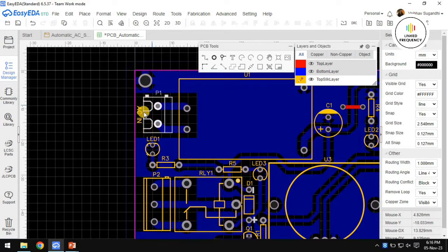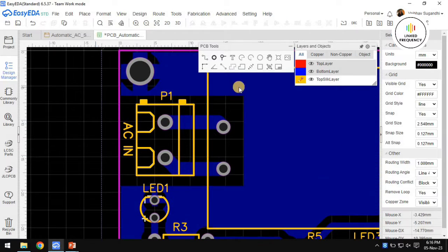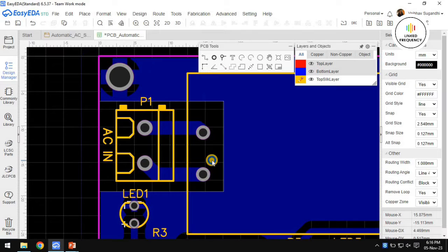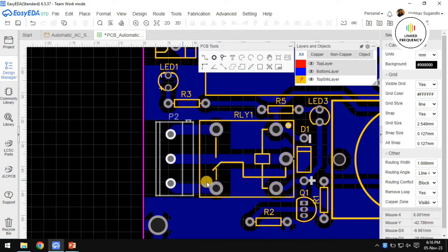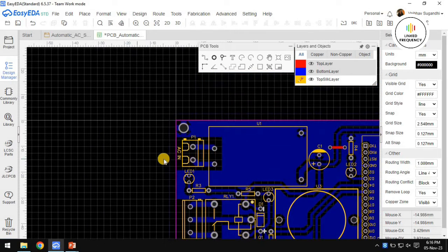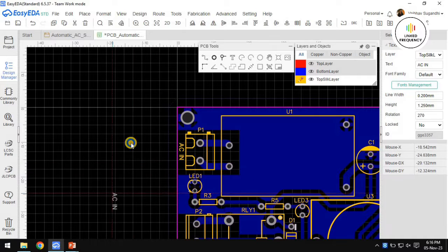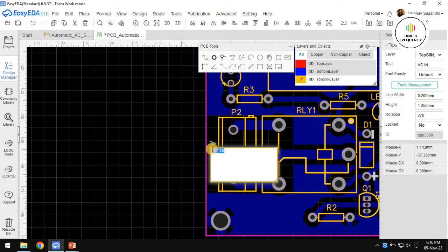Right now, we are not going to jump into detail about that particular thing, and we are not addressing that entire thing in this particular solid region option. But we are creating some security to our digital circuit by creating an exclude solid area for the ground. Similarly, for the AC switching, that is our relay module, we are creating the same solid region. That is the first thing that we learned in this particular tutorial. And the second thing is, let me finish this one as well.